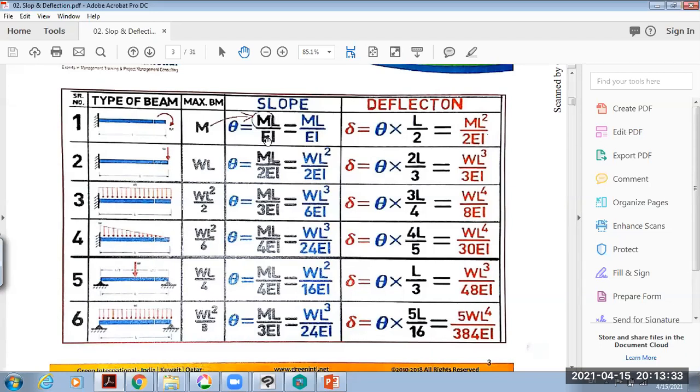Moment of inertia. Okay. Plastic has a modulus of elasticity different than copper, different than aluminum, different than wood, different than steel, different than concrete. So now, to reduce the slope, you use a rigid material. We call EI the rigidity. So as you increase the moment of inertia, the slope decreases. So the slope is a function of M and L, because this cantilever is subjected to a moment.